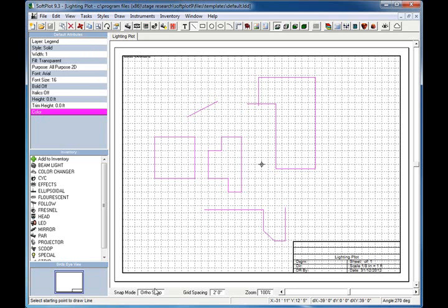Now you'll also notice there are control keys associated with snap grids. So it's possible I can use the control keys. I turn the snap off. I've started my line off the grid and off ortho. Now I'm going to turn it on grid using the control key. It's now on the grid. I'm going to switch to ortho using the control key. Hold the control key down. I'm suspended. Okay, so that is very quickly how to use the orthogonal grid snap modes.